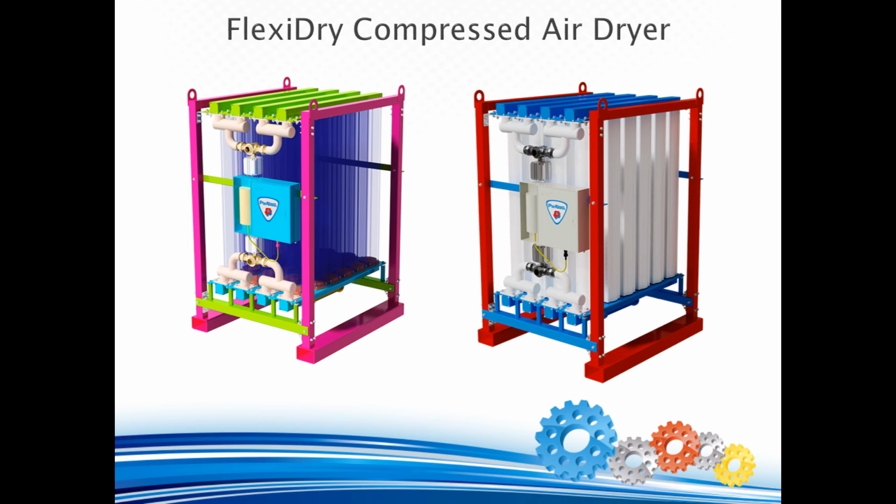Unlike conventional systems using fixed-volume steel pressure vessels for each dryer size, the revolutionary FlexiDry is a modular plug-and-play system that can be configured for flow rates ranging from 270 CFM to 4130 CFM using various combinations of two standard flow module sizes, Flexi 4U 275 CFM and Flexi 6U 410 CFM.